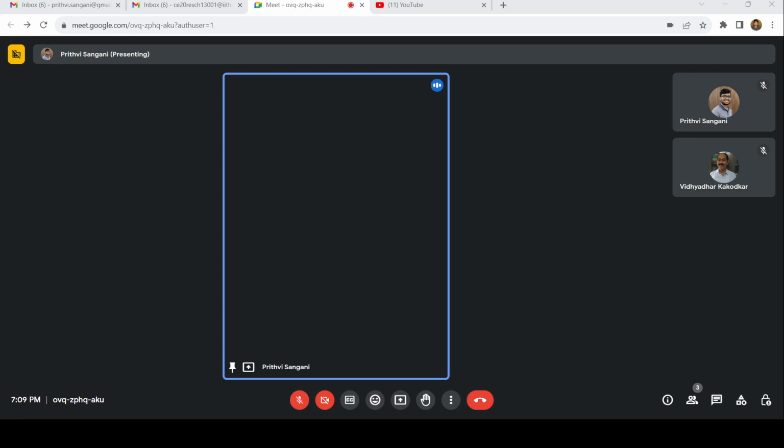So delta 2 is nothing but sigma ui square li by AE, this whole thing multiplied by HC. So ui square is minus 1 square into 8 divided by AE plus minus 1 square into 8 divided by AE, whole thing multiplied by HC, which is 16 by AE multiplied by HC.